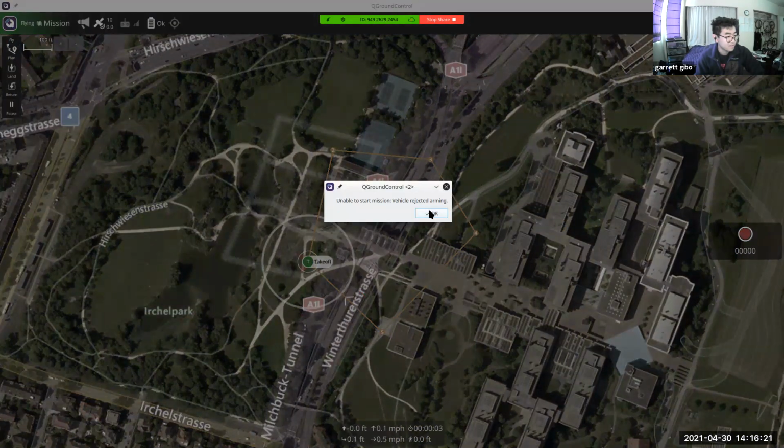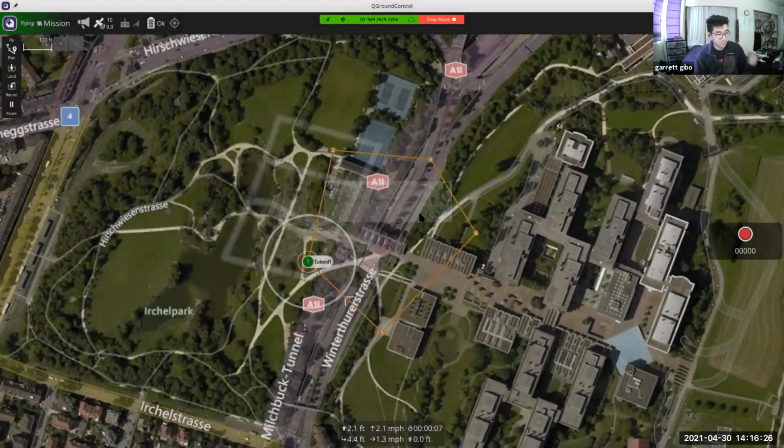You sometimes get weird unable-to-start-mission and arming issues when the controllers are first calibrating or they're unstable. If you have your controllers when you're actually implementing and they're extremely unstable, it just won't be able to arm at all and won't be able to take off, because PX4 has safety checks before it actually moves. That's preventing it from moving essentially.